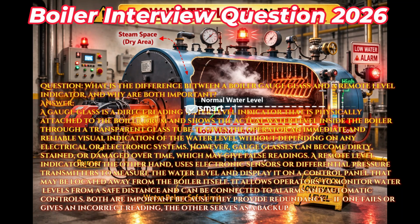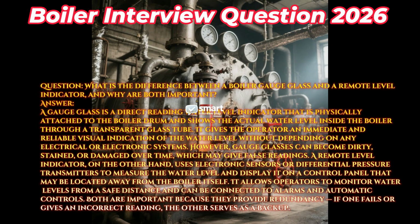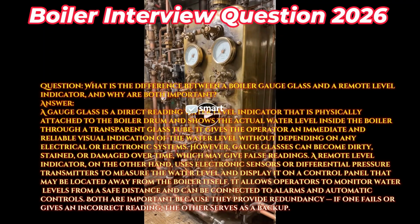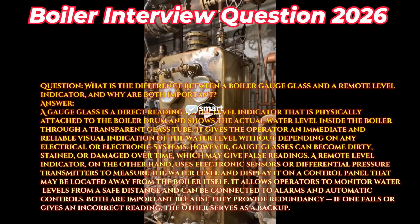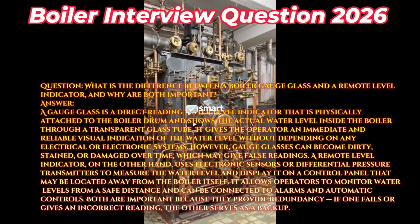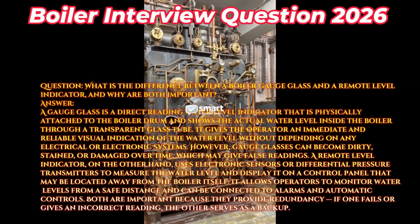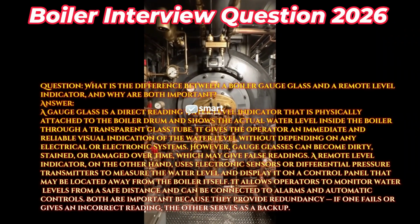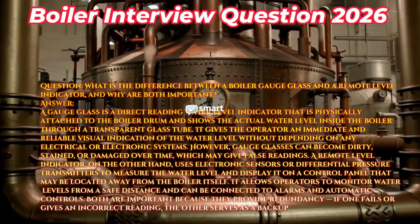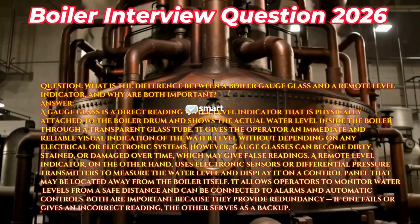A remote level indicator, on the other hand, uses electronic sensors or differential pressure transmitters to measure the water level and display it on a control panel that may be located away from the boiler itself. It allows operators to monitor water levels from a safe distance and can be connected to alarms and automatic controls. Both are important because they provide redundancy. If one fails or gives an incorrect reading, the other serves as a backup.